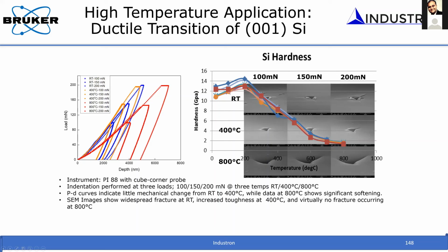This is mainly because of two competing mechanisms. One is due to phase transformation, another is dislocation based, because higher temperature can permit more dislocation-based deformation mechanics, whereas at room temperature it is more of a stress-induced phase transformation based mechanics.